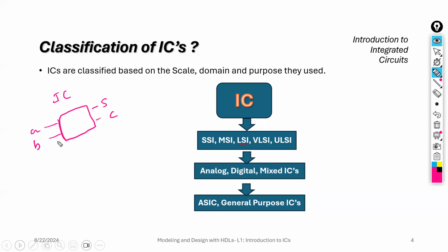But the general purpose IC is not like that. You can modify this particular IC by configuring another input. Or if you want to perform multiplication of A, B and C, it will produce only one output. Multiple applications can be done by the same IC. You do not create another IC for that. That kind of IC we call general purpose ICs, usually an FPGA, for example. We can implement any logical functionality in an FPGA. All right, good.